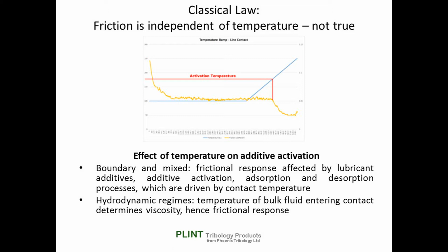In the hydrodynamic regimes, temperature of the bulk fluid entering the contact determines the viscosity. Changing the temperature, whether contact temperature or bulk fluid temperature, alters the shape of the Stribeck curve. In effect, one could plot a series of isothermal Stribeck curves if one was so inclined.